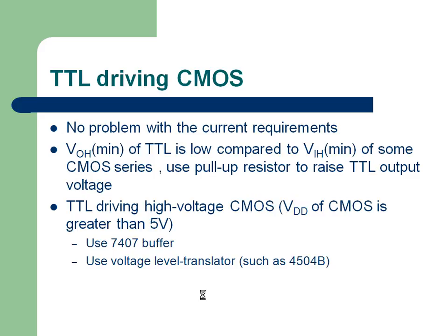What is it that you can do? See, when this is high, you can actually have a mechanism here. This is called a pull-up resistor. See, what is this pull-up resistor going to do? Let me take an example. This NAND gate is internally powered through, let us say, VCC equal to 3.2 volts, whereas this VCC is equal to 5 volts. So let's see what will happen. See, this is the internal circuit.